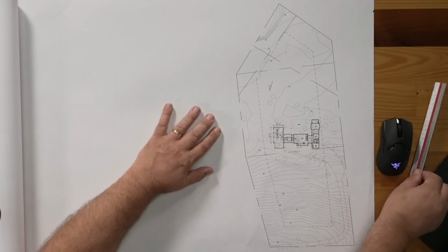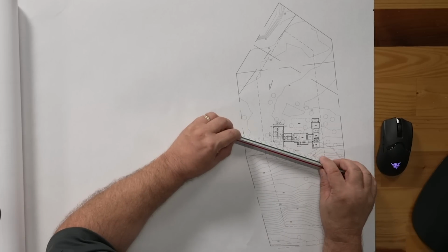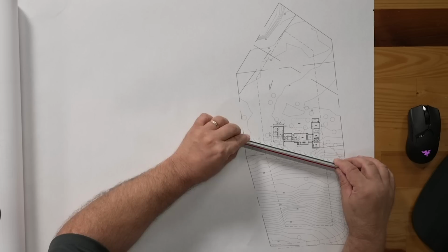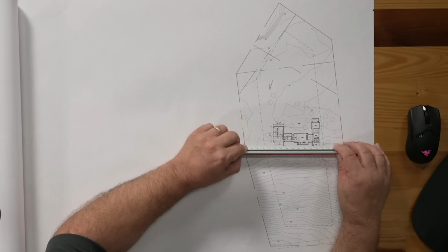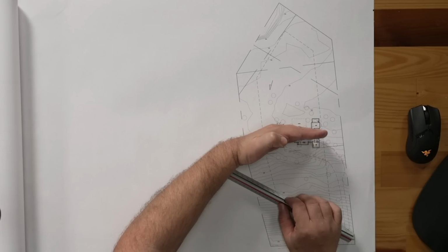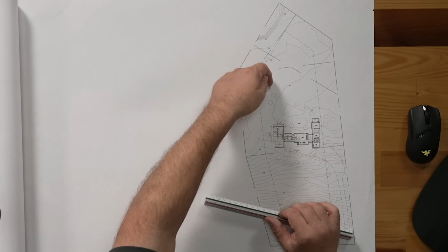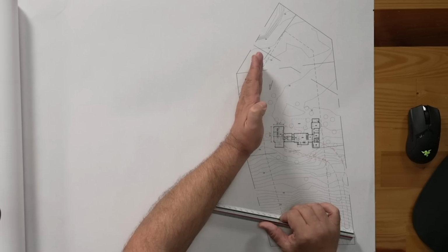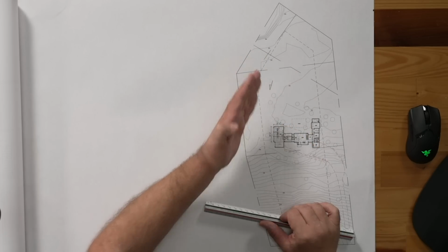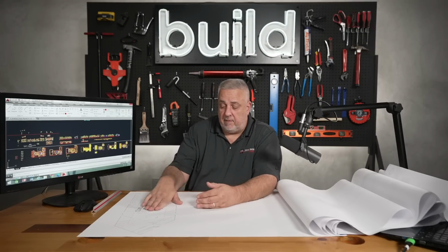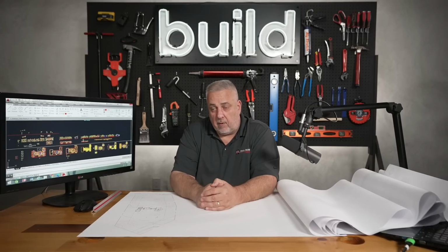You can see where the front of the existing house is on that plane, and now we've rotated it to that plane. So you can see that we've made that adjustment so that the south-facing roof becomes almost true south-facing instead of leaving it on that angle and being slightly off. That helps improve and optimize our solar access for our PV array located on the top of the garage.